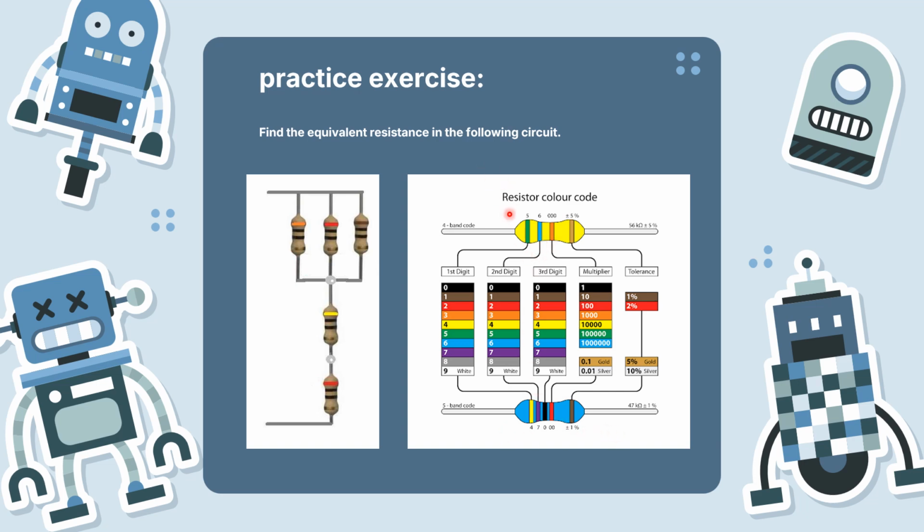In a 4 color resistor, the first and the second color represent the number, and we must directly find the number from the colors and write it down. And the third color represents the number of zeros, and as I said, the last color represents the tolerance.